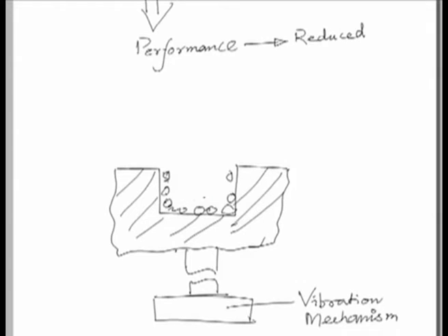will also be kept on vibrating because of the workpiece. So, this will hit the abrasive particles and keep them vibrating in the machining zone instead of getting clogged inside here, and the effectiveness of these abrasive particles will increase in this way. And since this will be kept on moving, there will be a possibility for new abrasives to enter this zone and for the continuation of this machining process.